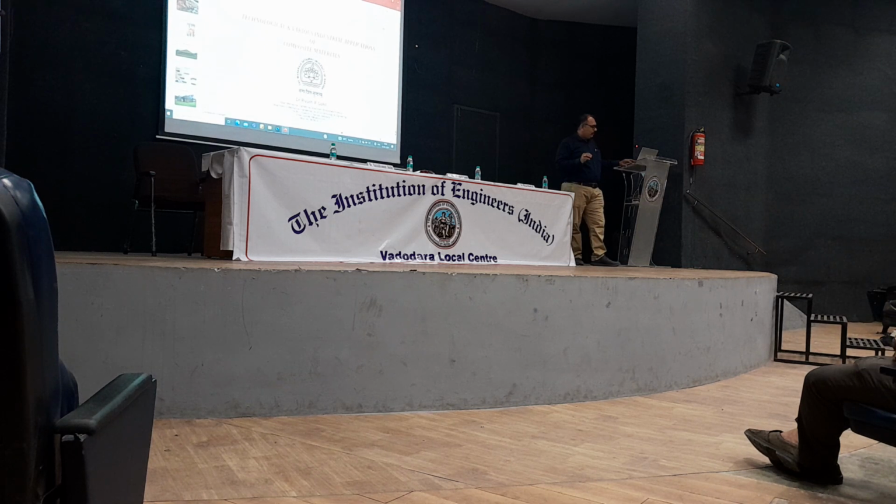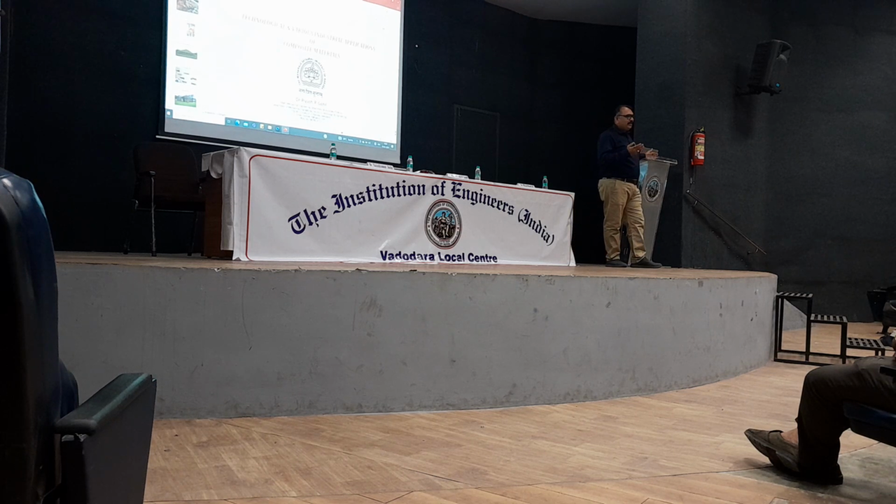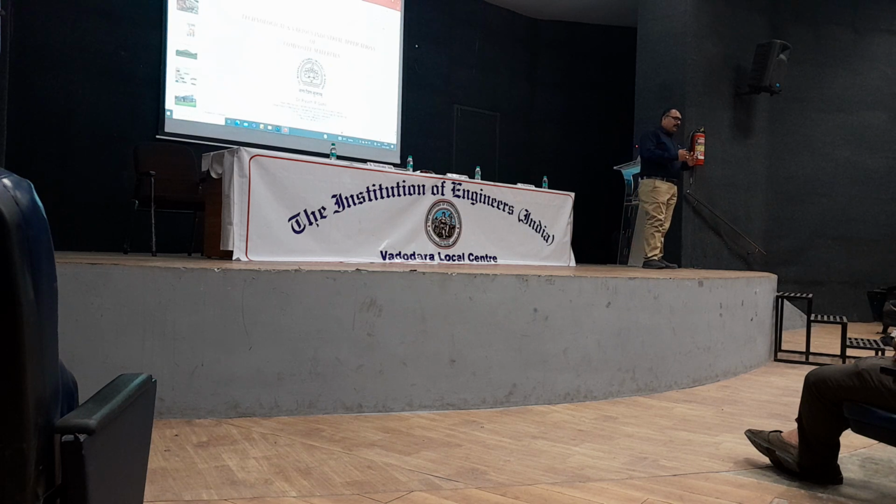One more thing in this composite field: when we were studying in the first year of engineering, after the beginning subject, we all heard the word factor of safety, 1, 2, and took it in our numericals also. But here that concept is not coming. Suppose a consumer asks what the reliability of this product is, how it will perform, especially in aerospace engineering, A-basis application and B-basis application, that is 99.9% reliability and 95% reliability. So we have to make sure that it will perform.